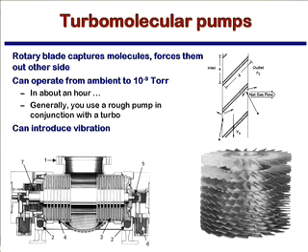You can use a turbo pump and still get to pretty good levels of resolution, but you have to isolate it pretty carefully. And so your turbo pump will be on top of a couple of big rubber gaskets and attached to a frame so that you don't introduce much vibration from this thing spinning around into your microscope column. They're also quite good pumps. You can go from ambient if you want, down to 10 to the minus 9 torr. Usually people do not go from ambient. Usually they rough the thing out to 10 to the minus 3 first, and then go down to 10 to the minus 9 torr thereafter. You will generally use these in combination, a rough pump first and then turn on the turbo and back it off. But you can get to pretty good vacuum pretty quickly with a turbo pump. They're a pretty nice way to go.